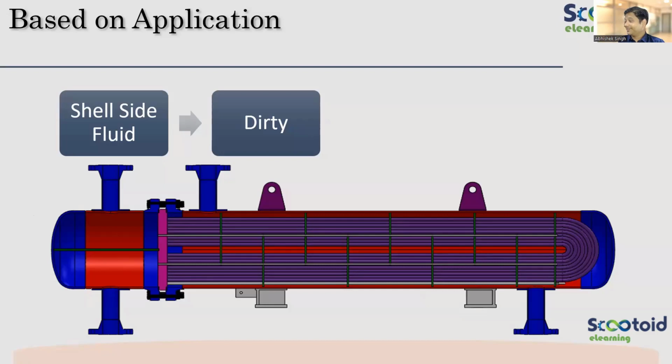Vaibhav, Harsh, all are saying no. Just think a little. Can I access the tube bundle? Jagdish is saying yes. Suraj is saying yes. See, I will be able to unbolt here, right? If I have to access the tube bundle, I'll do the unbolting here. I'll pull this tube bundle out by using this tube sheet, out of this shell. I'll separate it for cleaning, for maintenance.